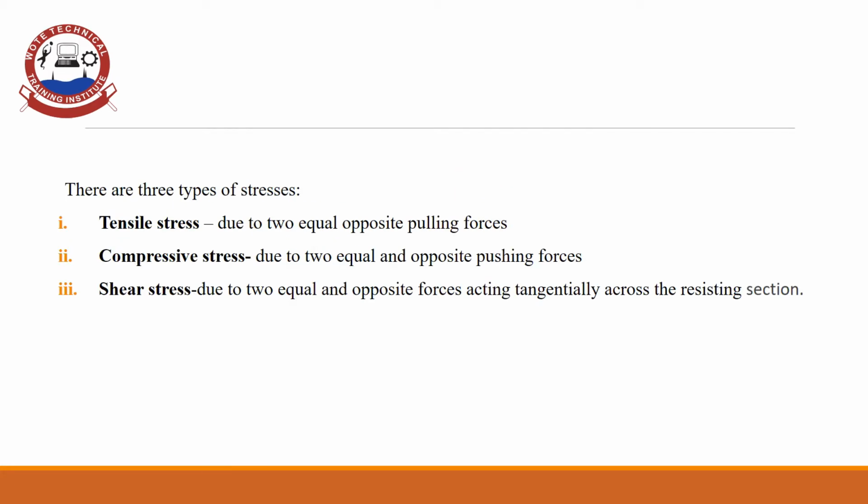There are three types of stresses. One, tensile stress, which is caused by two equal and opposite pulling forces. Two, compressive stress, which is caused by two equal and opposite pushing forces. And finally, shear stress, which is due to two unequal and opposite forces acting tangentially across the resisting section of the body.